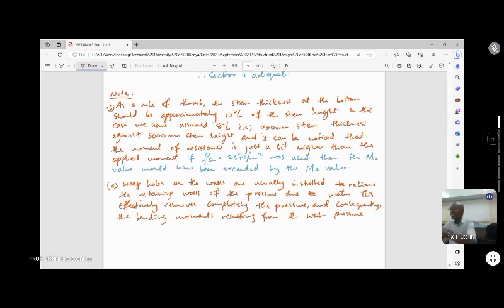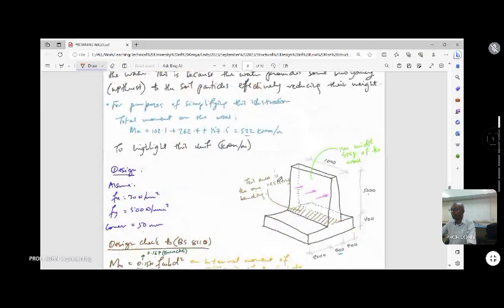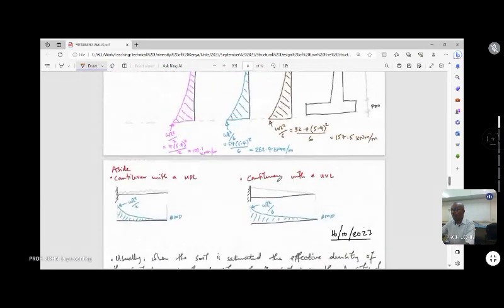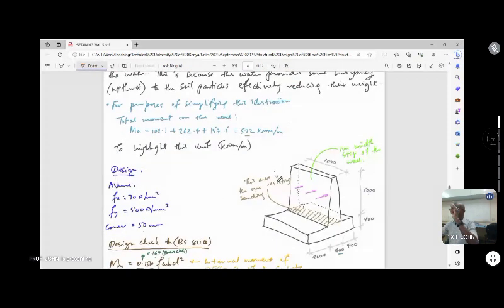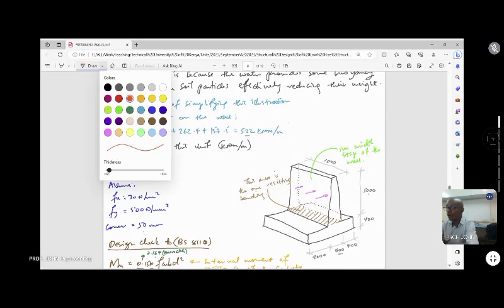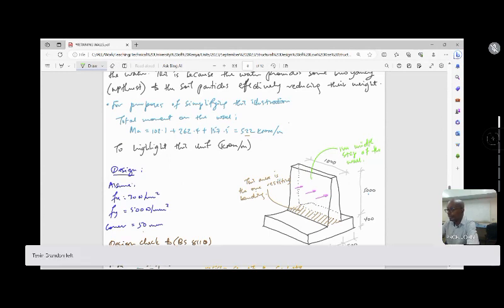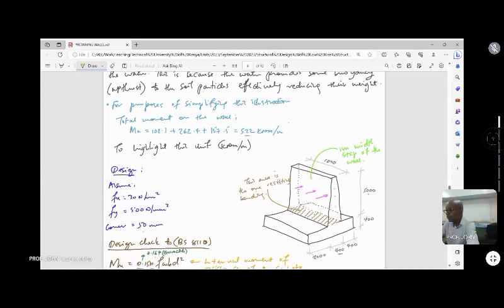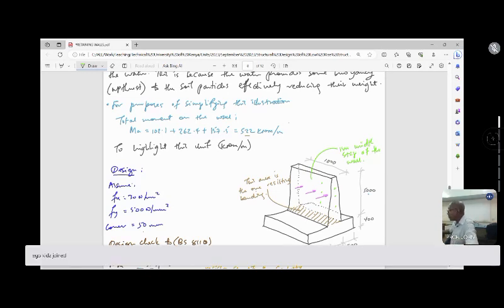So let's go back and look at the implication in terms of numbers. So the 262.4 is the loading due to pressure. So effectively, if we introduce weep holes onto this wall, just those small holes you see, they put at some intervals. When you drive along Thika Road, you look at the walls, you see they've got about 2-inch wide holes, and they are at intervals. And unless you are looking specifically for them, you will not see them because they are almost unnoticeable.